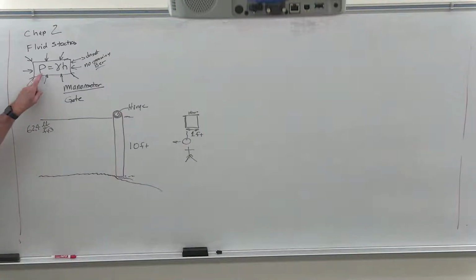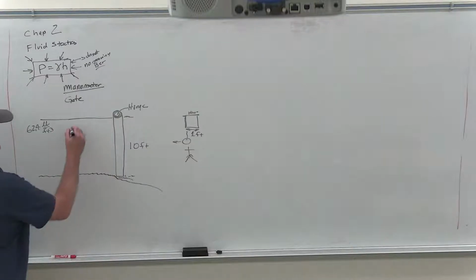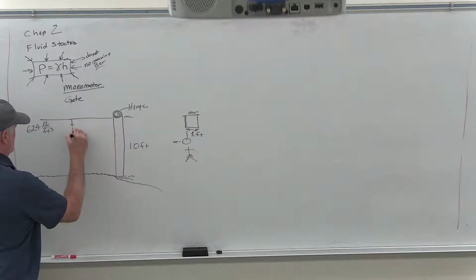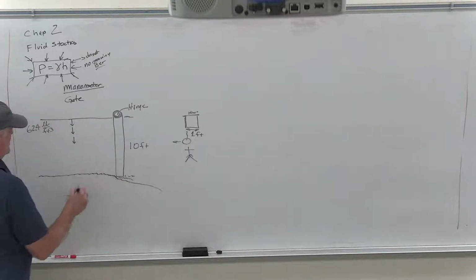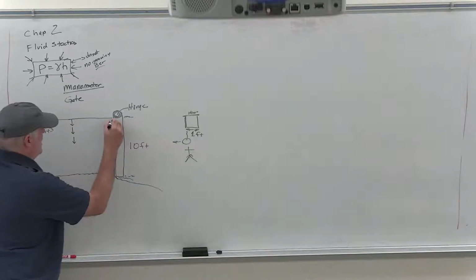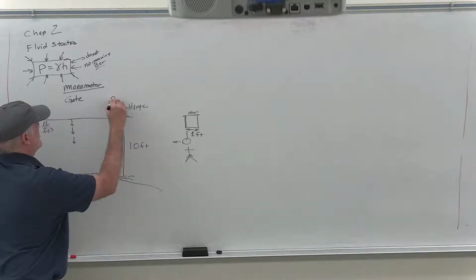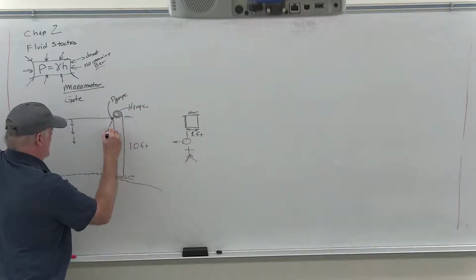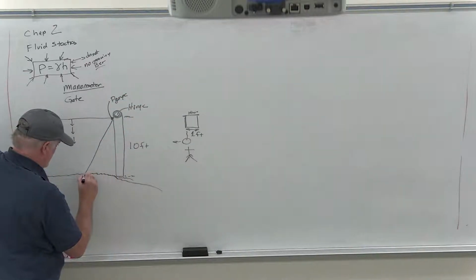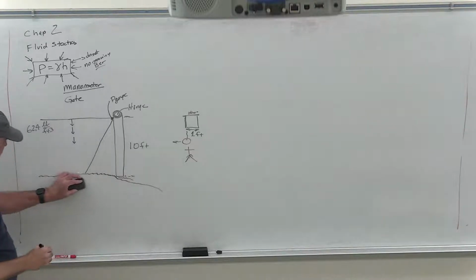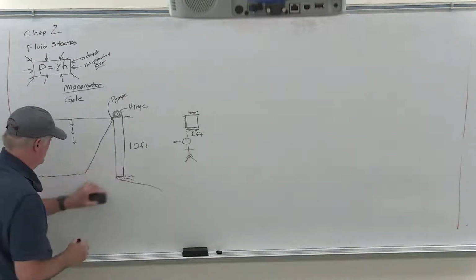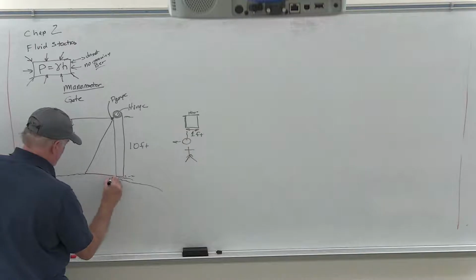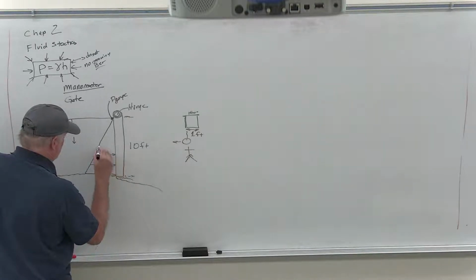So we know that the pressure varies with depth. The further we go down, the higher the pressure is. So if we want to plot gauge pressure, then what we would have is this linearly varying pressure, which basically starts at the top, increases, and looks like that.